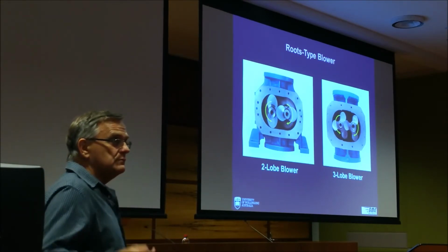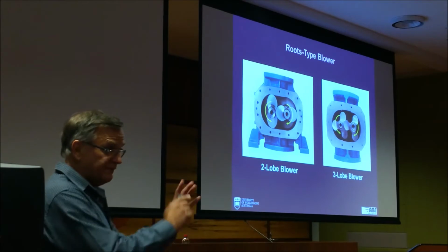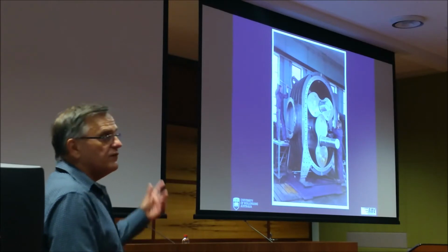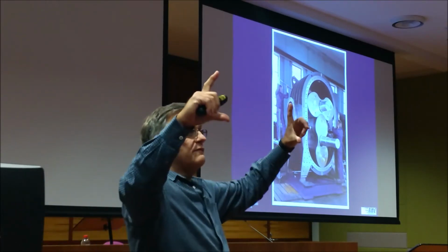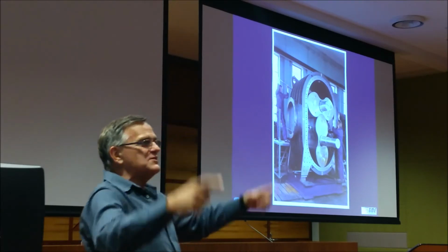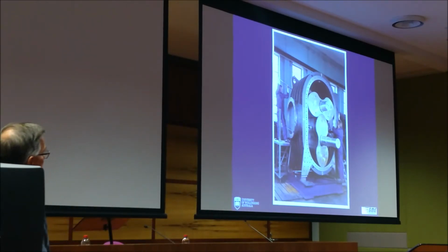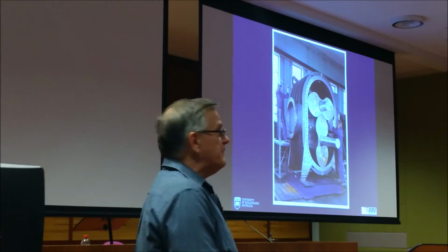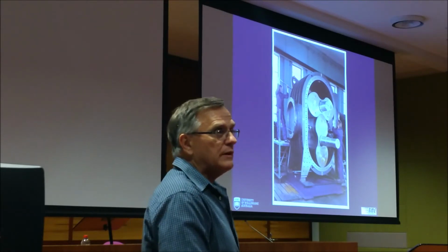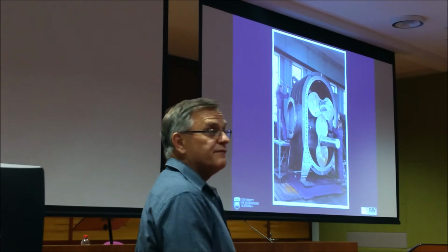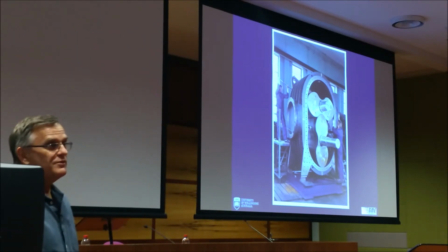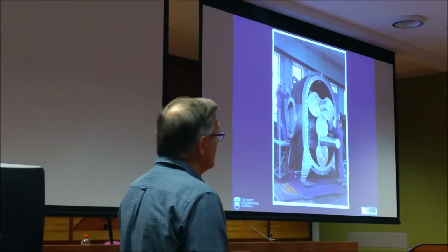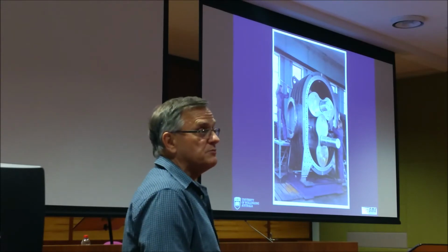And blowers can be quite big, and it becomes more challenging to assemble and fit a blower. So this one is probably one of the biggest that you'll see in the world. These are used on pneumatic ship unloaders, pneumatic conveyance with pipes about that big, sucking up a lot of product out of the ship. Again, you need feeler gauges to get those clearances correct. If you have any metal contact in there, these blowers will self-destruct pretty quickly. Imagine these shafts running at 500 or 600 RPM at that size. That's pretty scary. But it can be engineered, precision manufactured, and you can get it right, allowing for thermal conductivity and expansion.